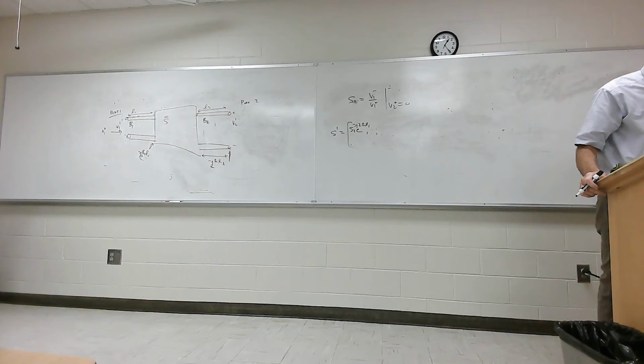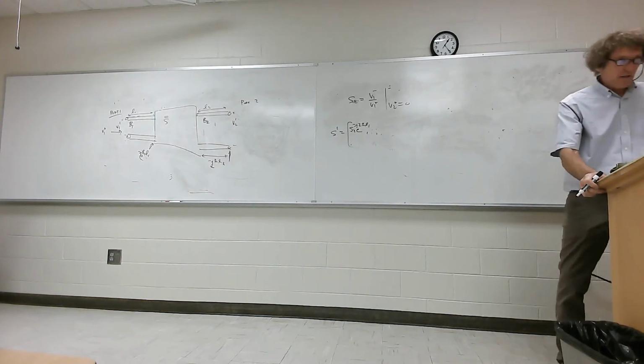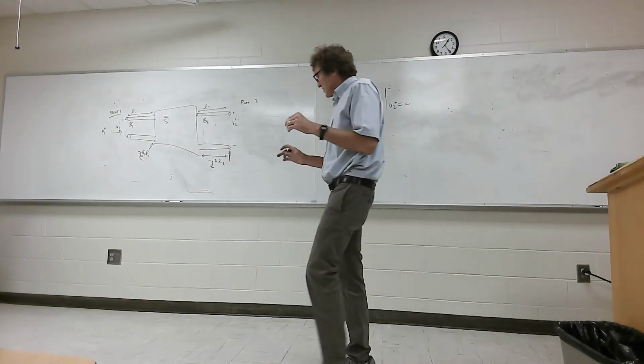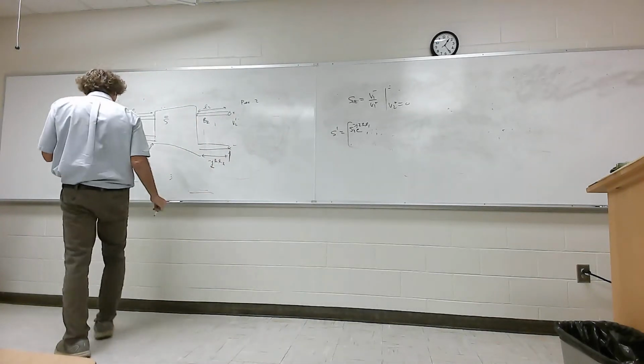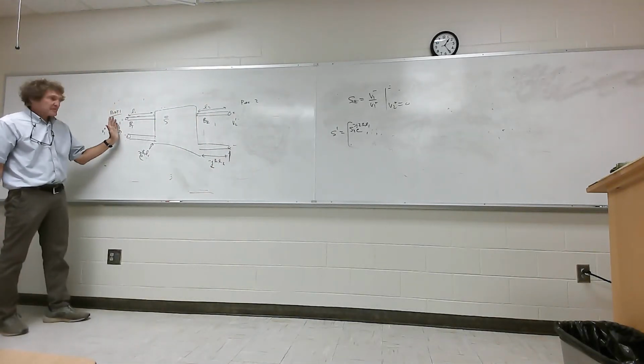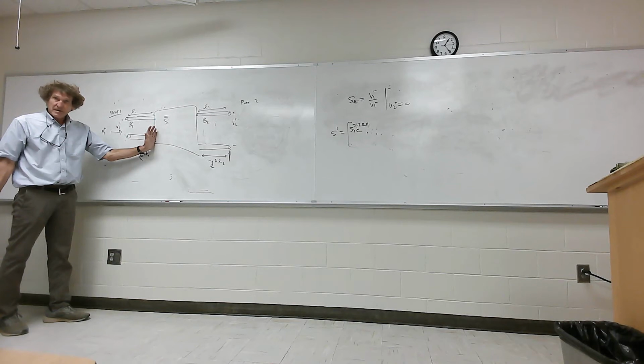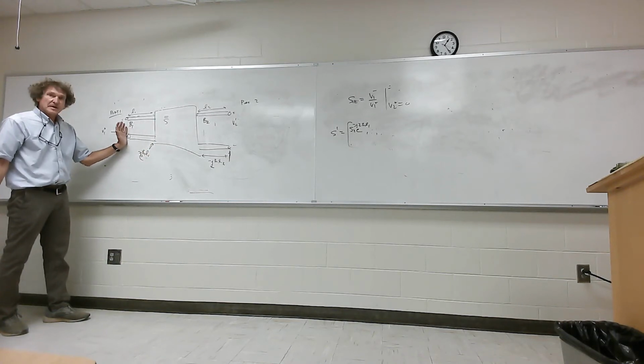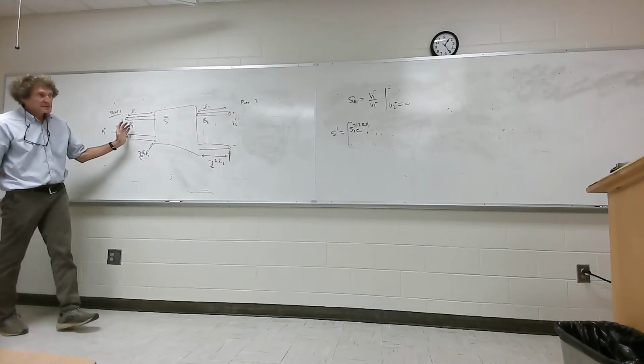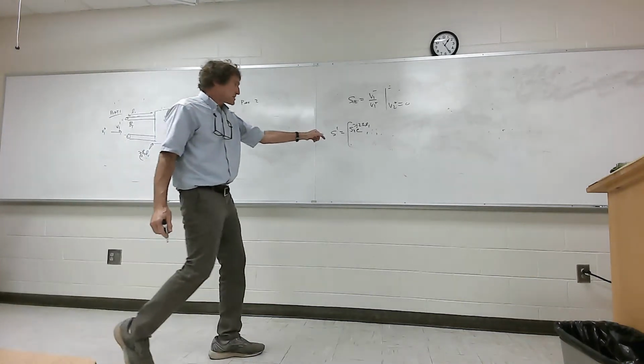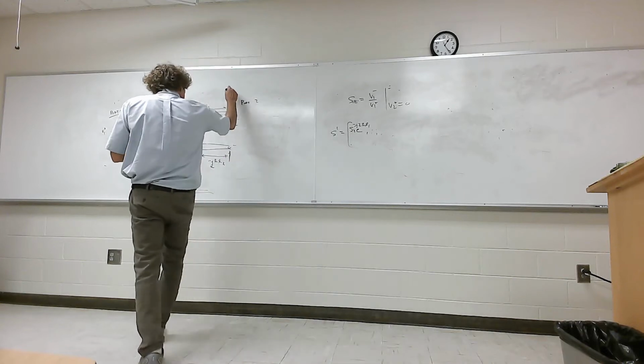He calls it S prime, equation 10.35. Just understand that the only thing he's doing is accounting for the phase difference, because the wave came down here before it hit here. Then you have to multiply by the S parameter, and then there was a continual phase change when it got back here. So that means these S prime parameters are for the outer region here.